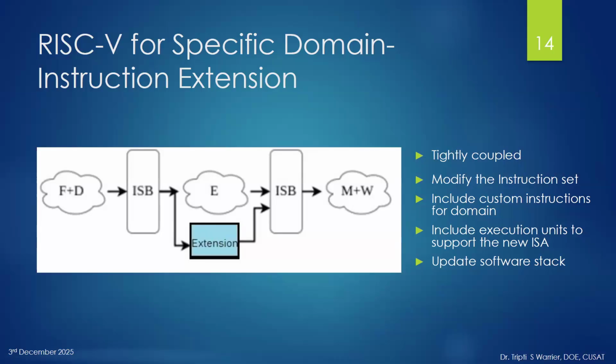That is, in C code, you can embed assembly. You can force a call of an assembly instruction using volatile. In that case, the person developing the application has knowledge of the hardware and of the domain, and purposefully replaces C code snippets with extension instructions which will speed up the process. So if the compiler doesn't support it, this has to be done.